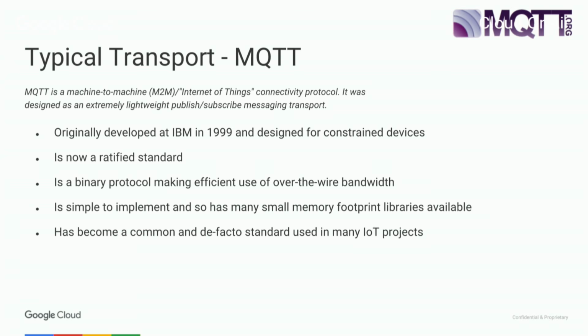And because the devices are typically small, and the network connections you have are restricted bandwidth and maybe more expensive, using the full-blown internet TCP/IP, HTTP, HTTPS stack would be very heavy on those devices. And many of the microcontrollers cannot really handle the full internet stack. That's why it's really popular in the world of IoT to use MQTT as the transport protocol.